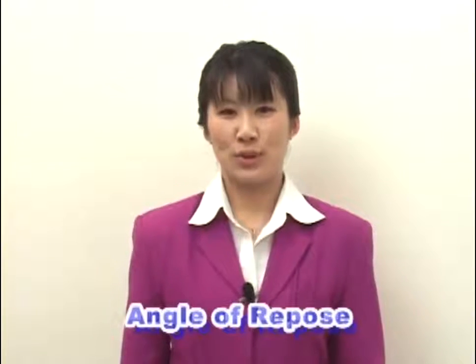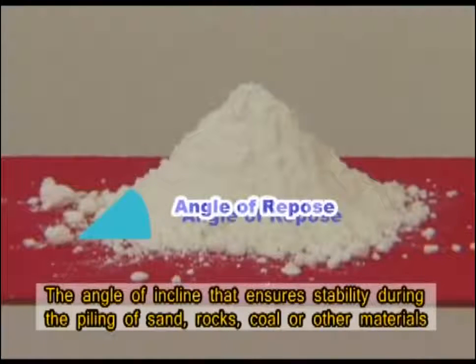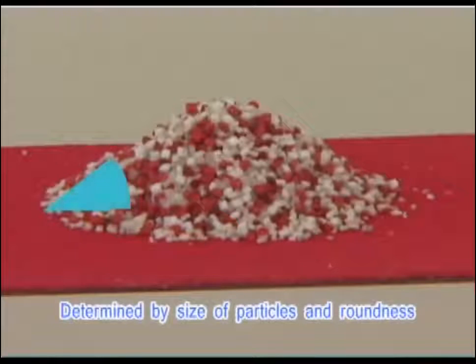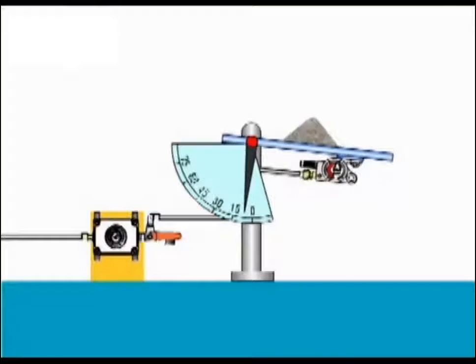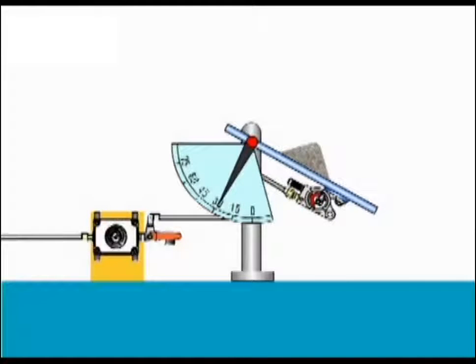Here we will describe one more cause of blockage. Are you familiar with the angle of repose? The angle of repose is the angle of incline that ensures stability and prevents unintended collapse during the piling of sand, rocks, or other materials. This varies according to the size of the particles and the roundness. If the angle is not greater than the angle of repose, the powder and particles do not flow.